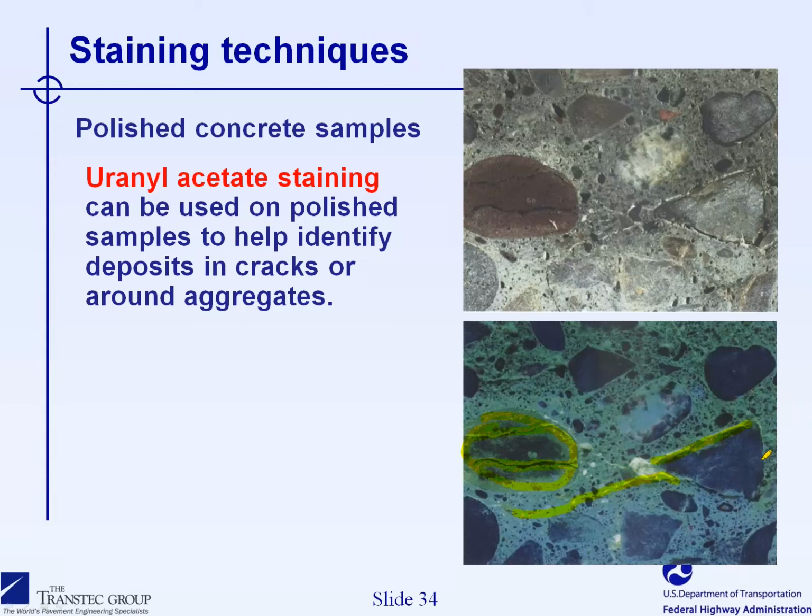Sometimes the gel will pass at the border of the aggregate particle. In this case, it is happening like that. But as I said, generally speaking, when you have an alkali silica reactive material, you will see cracks in the aggregate particle. The presence of gel will be a function of the reactivity of the aggregate and also, unfortunately, sample preparation.